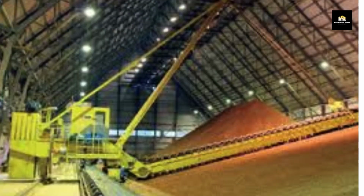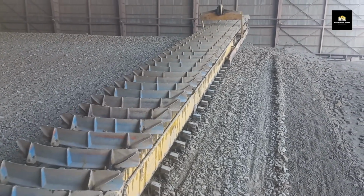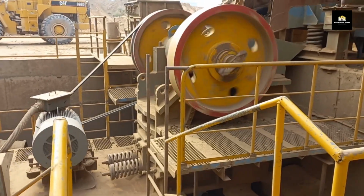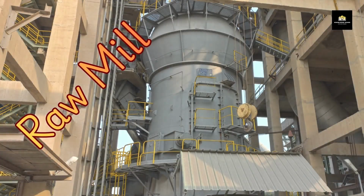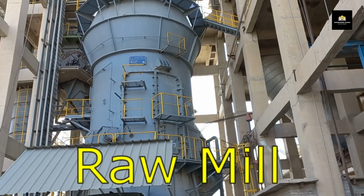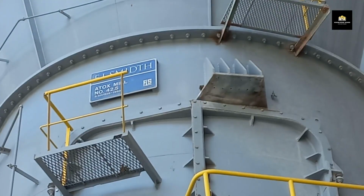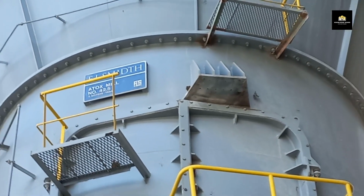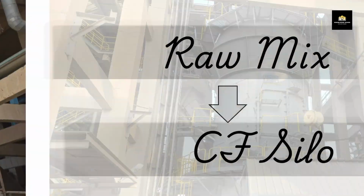In the wet process, each raw material is quarried, crushed, and stockpiled separately to provide feedstock of known composition. The second important step after crushing of raw materials for manufacturing cement is grinding of raw materials in the raw mill in appropriate proportions, where it is finely ground into powder. Grinding increases surface area, making chemical reactions more efficient and ensuring a consistent composition.